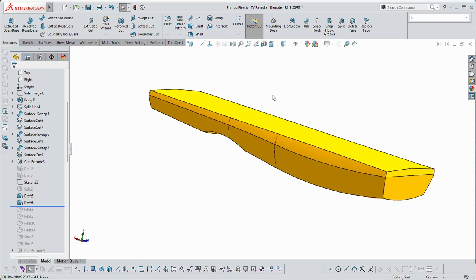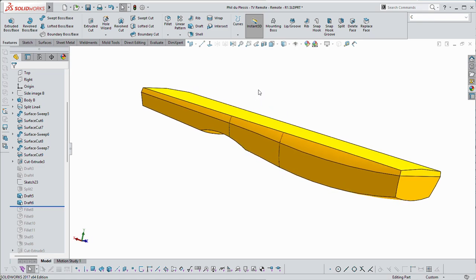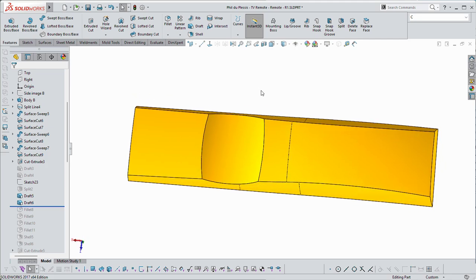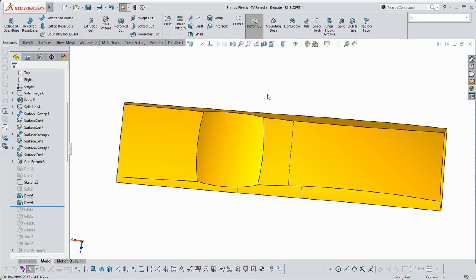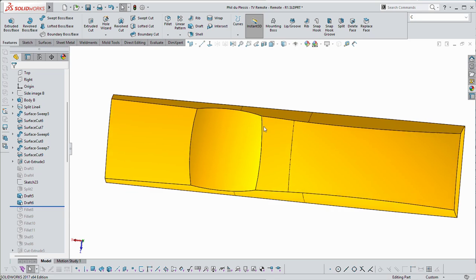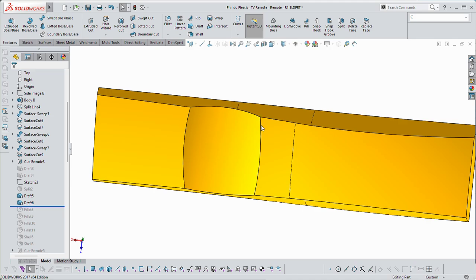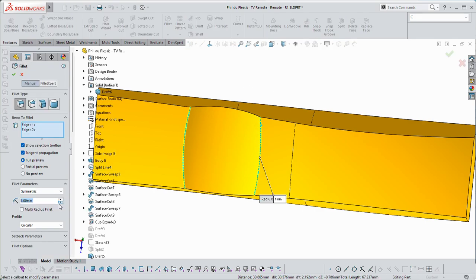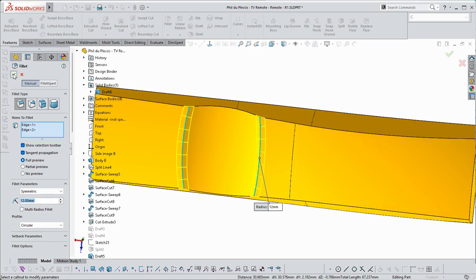All right, now the next step is to put the fillets in, and the rule is go from your largest fillets to your smallest, and that's because, as I explained in class, which I'm not going to explain here, you want the fillets to flow across certain directions across tangents. So I'm going to select these two first because these are going to be kind of guiding where the other fillets go, and at the moment it's at 1. I want it to be nice and large, about 12.